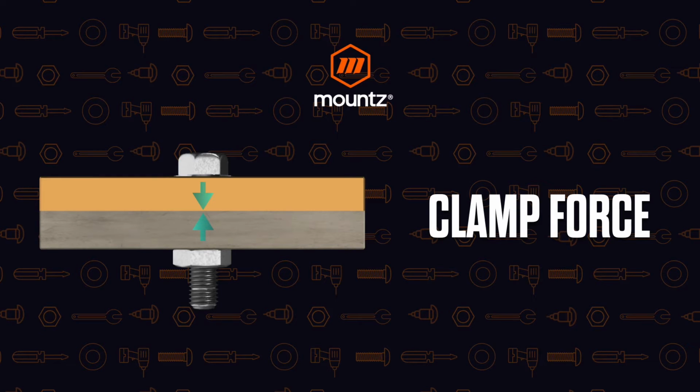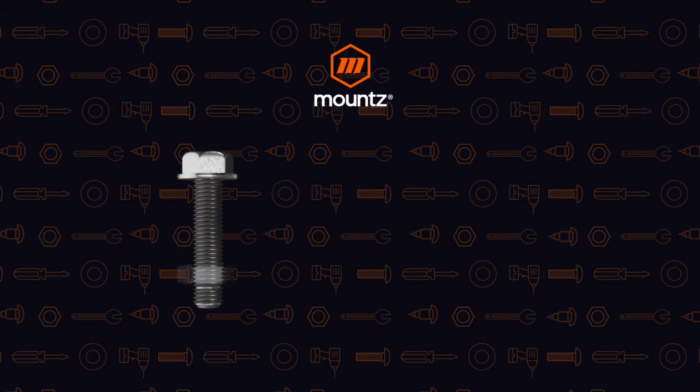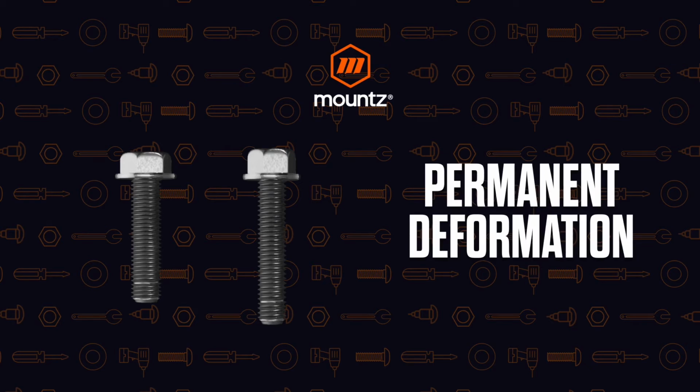So if we take a look at what would happen if we did go past that, if we remove the fastener and the nut, we see that the bolt goes back to its original shape. However, if we were to then remove the material and we saw that the bolt has now been elongated, then we have permanent deformation, and that particular fastener has gone past the yield point.